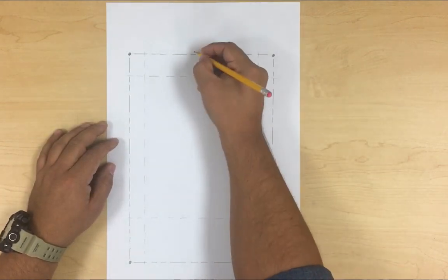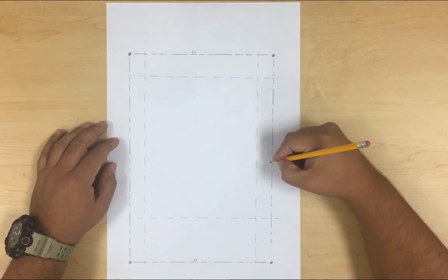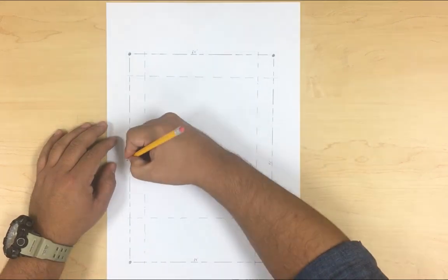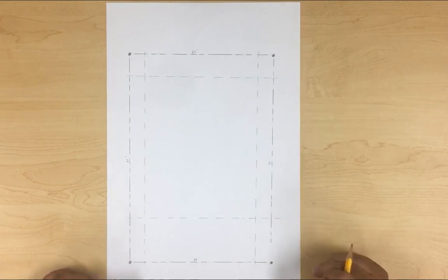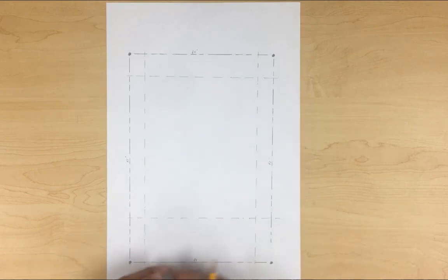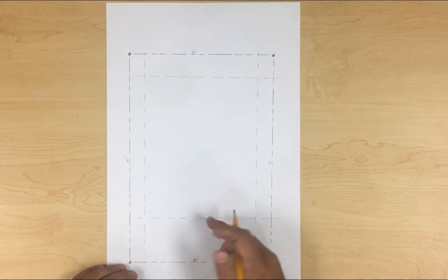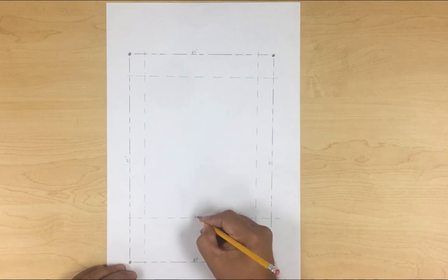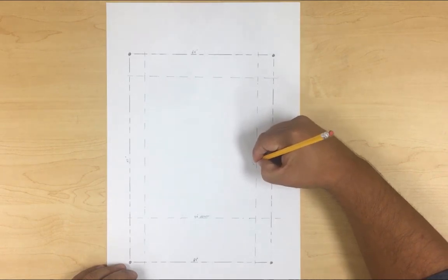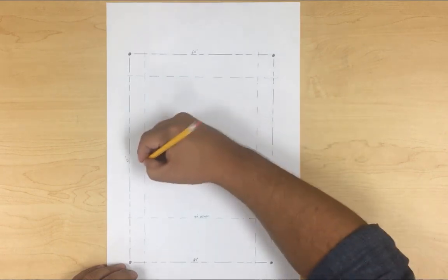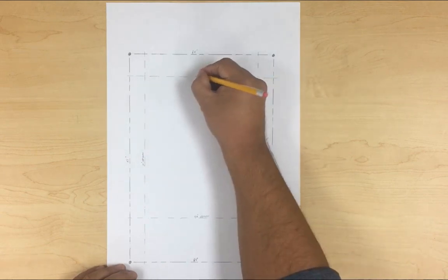Here we're just going to put the size. We're going to put 64 feet, 64 feet, 95 feet, 95 feet. Again, this will be the bearings, but I don't have them. If I find them, I'll upload them on Blackboard. I don't know the exact bearings, but I know the size right there. And then here we're going to define what these lines mean. This is a 20-foot setback, 7 feet setback. Same thing here. So you have to label it. And the back is 10 feet.